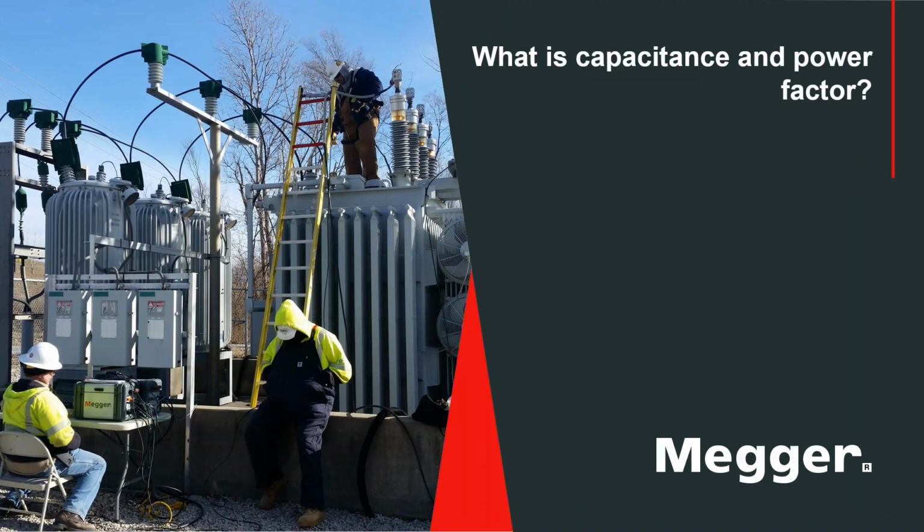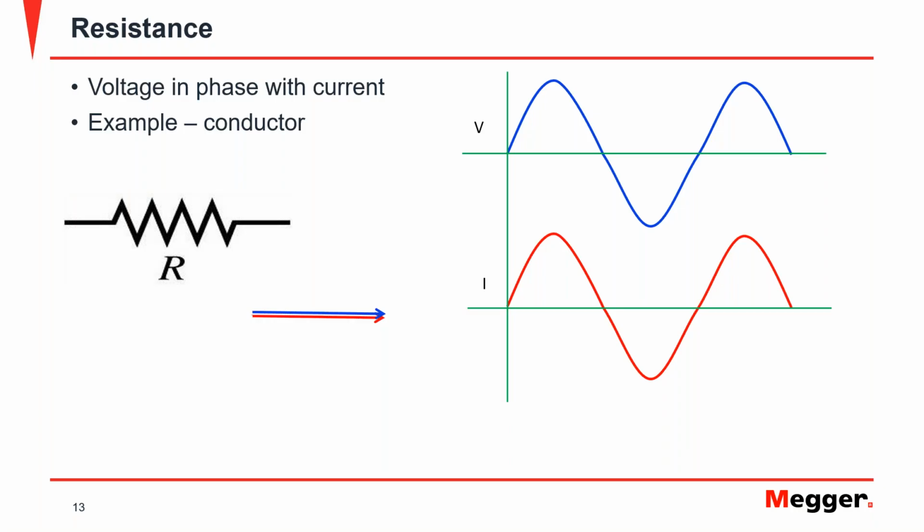So let's start off from the very basic. Let's talk about what is capacitance, what is power factor. Let's try to understand these terms. There are three types of elements. You have resistance, you have inductance, and capacitance. The way these behave when voltage is applied across them is different. When you apply voltage across a resistance, the current that you get out of a resistance is in phase with the voltage, right? An example of a resistance is the conductor. So copper or aluminum, it could be in the form of a cable, it could be in the form of a bus bar, but essentially that's a resistance.